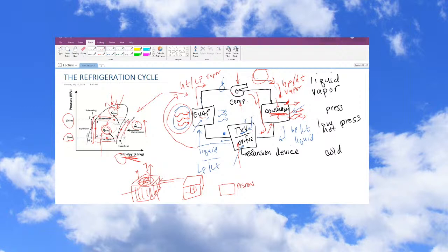Low side pressures. Curious if you demonstrate variable displacement compressors. I mean, for like home stuff, are you talking like the Waterbury pumps, for example? I'm not sure that's what he's talking about. So if you wanted to, instead of just controlling your pressure based on action of the TXV, you could also change your compressor ratio, your compression ratio, essentially. I've never seen the Waterburys before. That might be what he's talking about, the Waterbury pump.